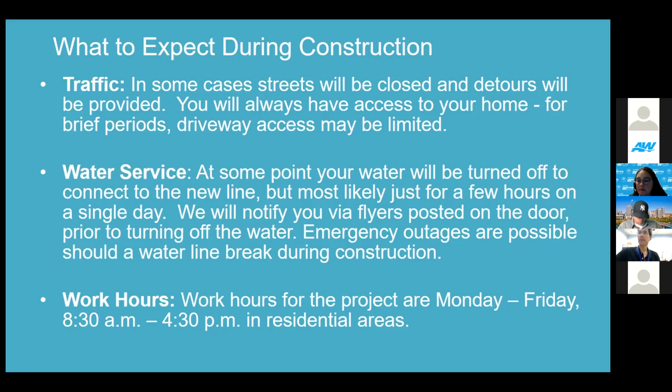So effectively, it should reduce the pressure at the meters for each property in these two neighborhoods by about 60 psi. Maybe not an exact number, but approximately 60 psi. So if you have an individual PRV that's been working this whole time, you shouldn't have to make any adjustments to that. It's really to reduce the system pressure so that we experience fewer breaks in the future.